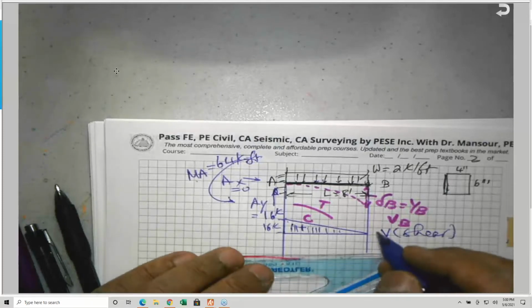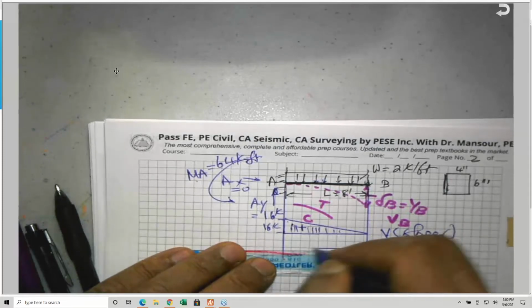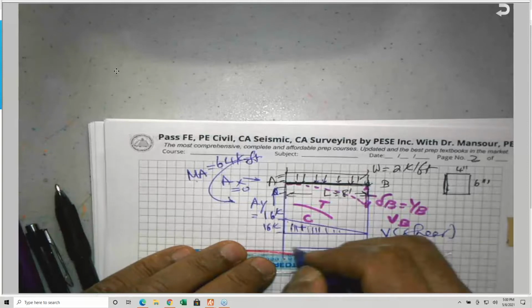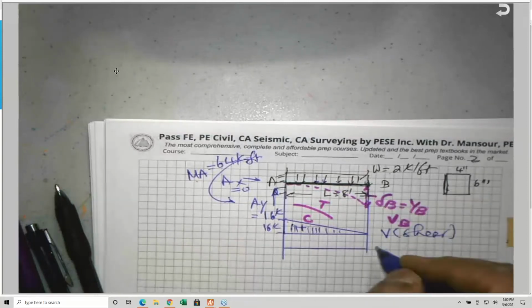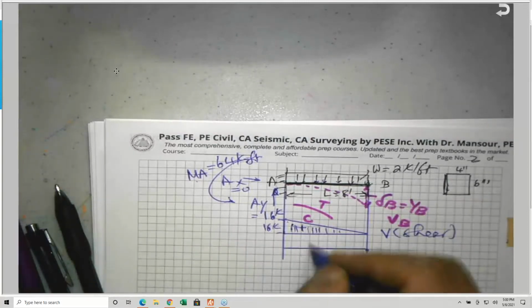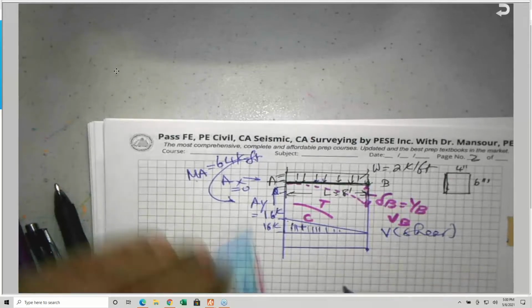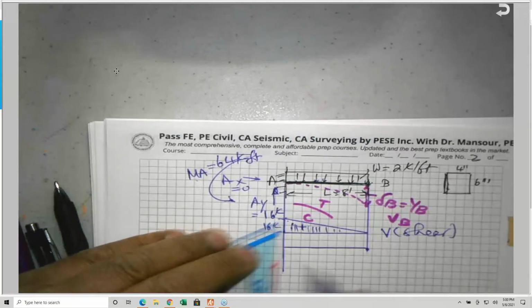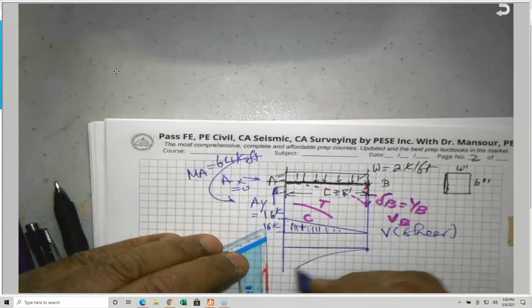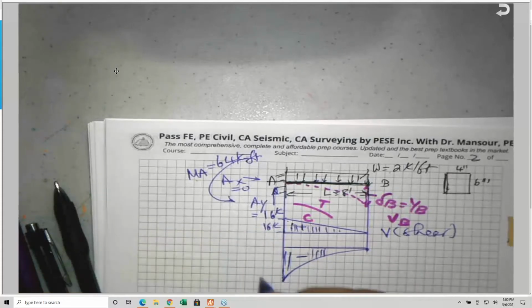The bending moment diagram, since it is negative, normally we draw a reference line, we call it datum. So the bending moment here is equal to 0 at the free end, and the bending moment is one degree higher than the shear. So in this case, you'll find this is a second degree parabola, like that, and it is a negative bending moment as we indicated because it's an unhappy face. And this magnitude here is 64.